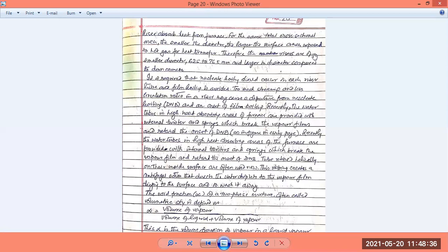If steaming is too much and the circulation ratio is less, too much steam is going out and comparatively less water is coming through the downcomer to the riser. There may be a formation of film on the riser tube itself.